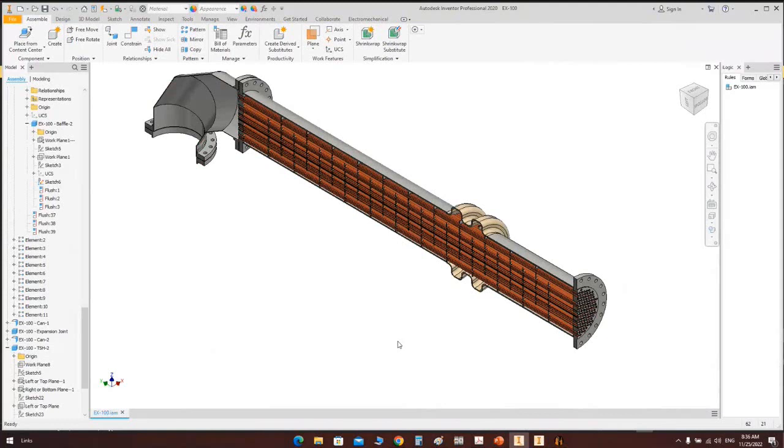Another question is, how can we use the baffle impingement option, tube row option, sealing strip option in tube sheet bundle design that you have given in the SEG software? Okay, during the session, inshallah, after creating the nozzles, we can add or discuss the available different types of impingement baffles, okay, and how we can add them. And if you would like to add, let's say, impingement baffles as rod, how you can do that, how you can add spaces. I have many questions about tube sheet design.